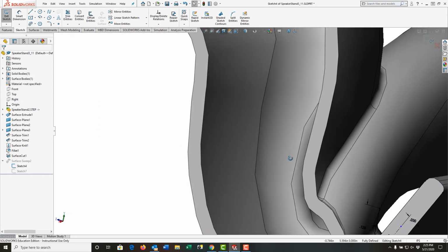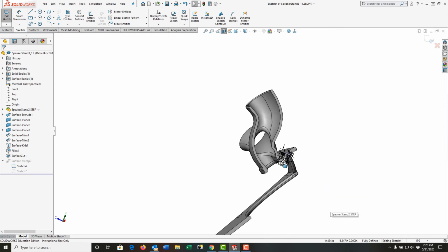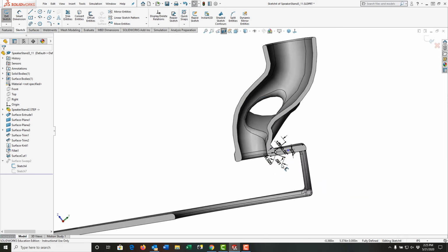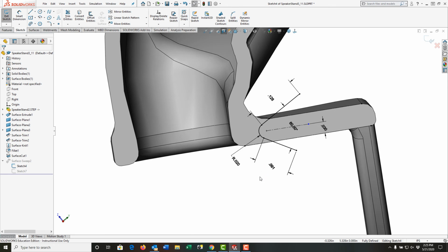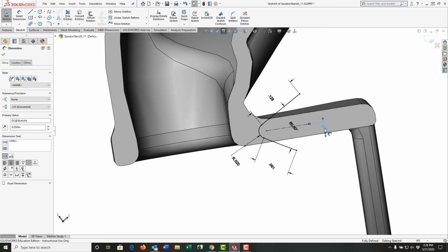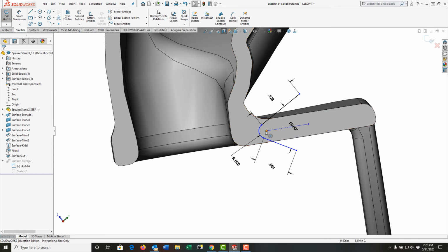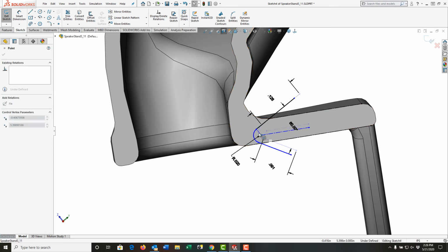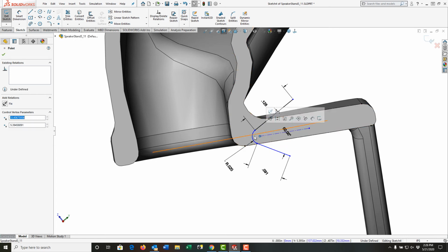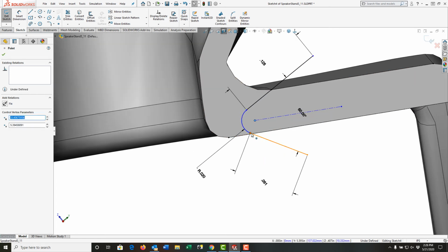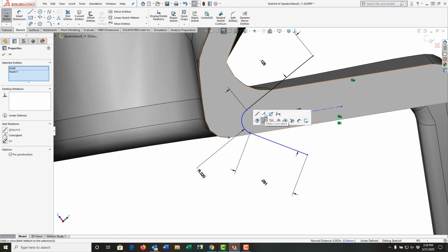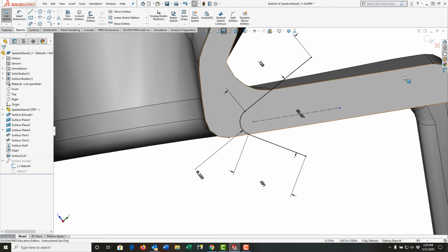So I want to look at what's keeping it there. Just want to zoom around a bit and get a nicer position to look at. What I need to determine is the sketch is fully defined, so what will allow me to pull it this way? I'm going to try deleting this 30 thou dimension, and now I see I can move it around, but I want to be careful. I'm not overly happy, but what I'm going to try now is I'm going to take this point here and I'll make it coincident with this converted edge. So I'm going to say OK.